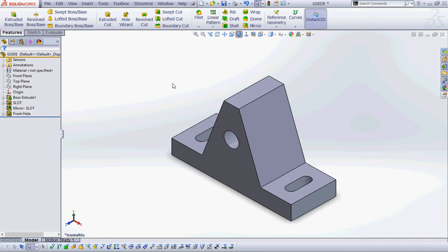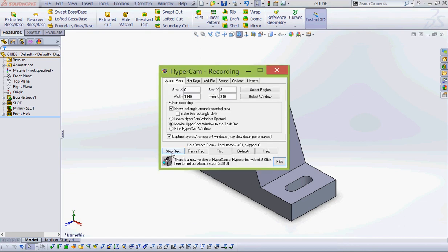Okay, so let's do it again. I'm going to select the mirror tool, and then I drag right here. And I drag it down to reveal a hidden browser behind my properties pane, and then fill in my boxes and then green check. Is that cool? And then I'm just going to rename this so I know what it is, and save.